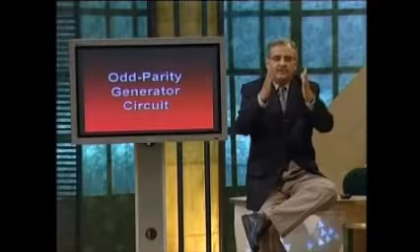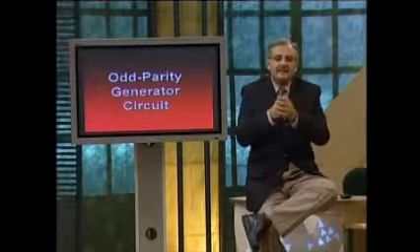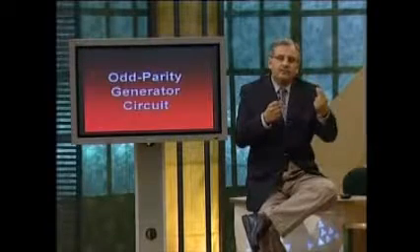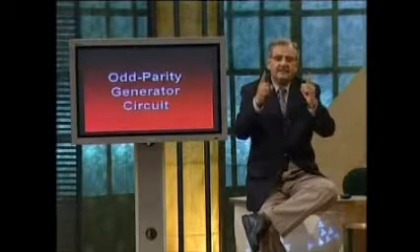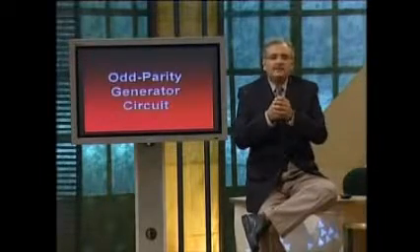अगर जो 4 बिट डाटा है उसमें जो number of ones हैं वो odd number है, 1 है या 3 है, then the parity bit would be set to 0. So the total number of ones in the 5 bit data remains an odd number. Now सर्किट जो है odd bit parity generator का कैसे बनेगा? Well, let us just discuss that.